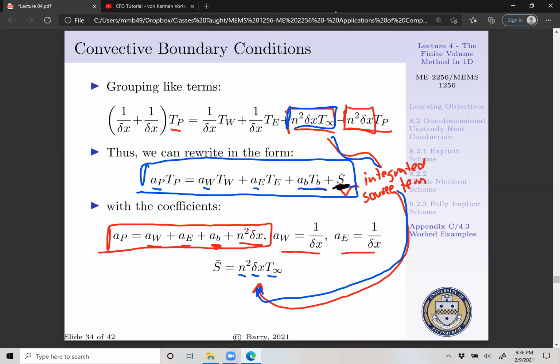So we'll combine both of those, and we'll talk about the tridiagonal matrix algorithm, the pentadiagonal matrix algorithm that's used to solve those coefficient matrices quicker and faster than just brute force inversion. And that will hopefully get us into a really good position to start learning some of the numeric tools to handle these types of problems, generate the meshes, run the models, post-process the results compared to our codes. And that would really set us up to move into flow.